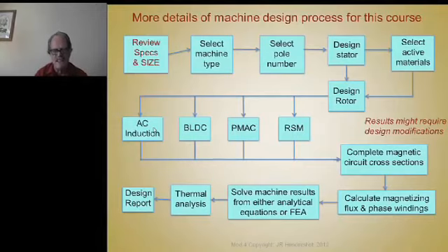In the case of the induction motor, your peak torque determines the maximum magnetizing flux and the maximum magnetizing current. So in the rotor design, you have to balance the cross-sectional area of the copper for the cage with the cross-sectional area of the steel to carry the flux for the peak torques. That's the key.